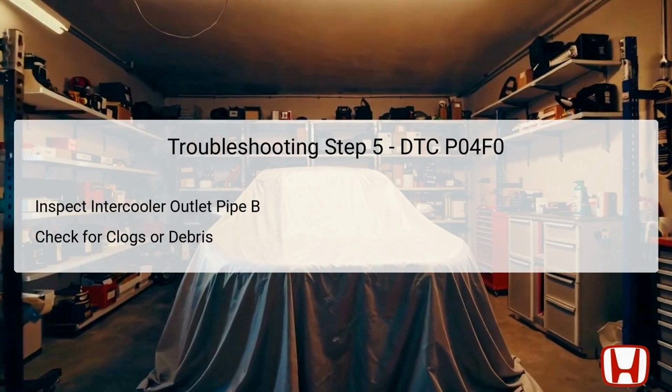Ensure that the pipe is clean and free of any physical obstructions. If any issues are detected, they must be rectified promptly to ensure optimal airflow and compliance with emission standards. The penultimate step involves checking the evap canister purge nozzle, an essential component for controlling vapor flow from the canister to the engine. Begin with a preparation step ensuring Purge Tube B is disconnected from the nozzle for effective inspection.